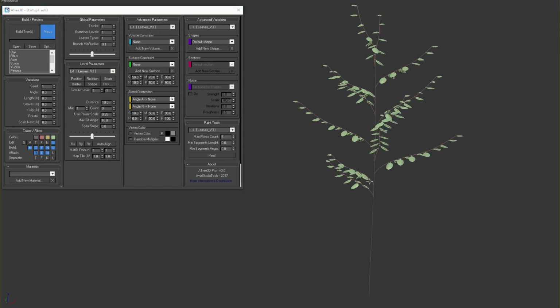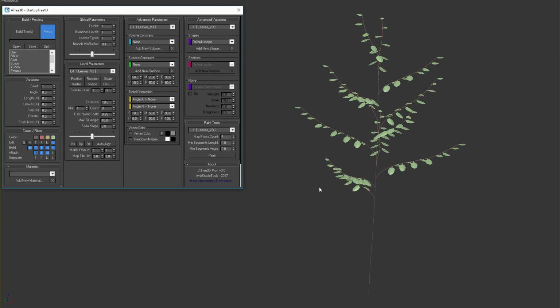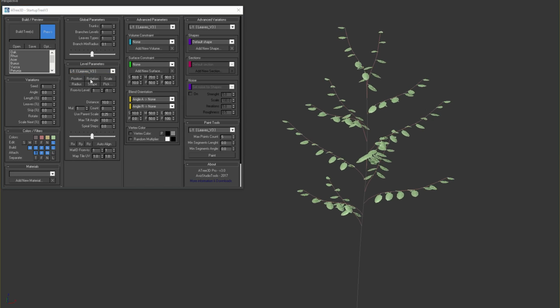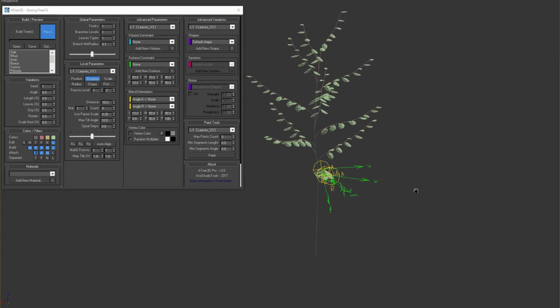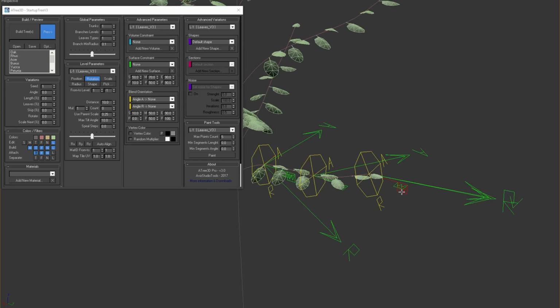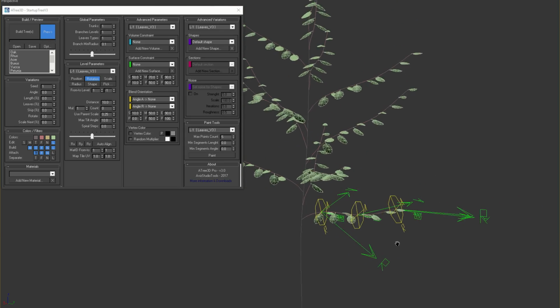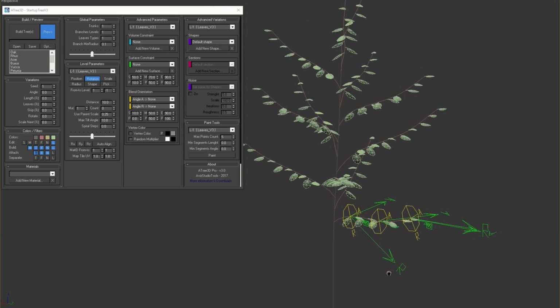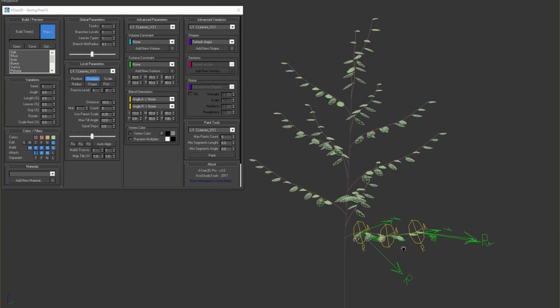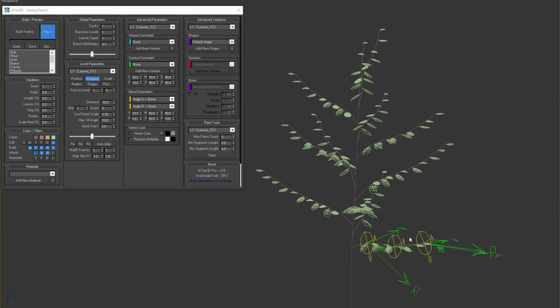Let's continue with the next parameter, Blend Orientation. In this tree model, the leaves are aligned to the world. By pressing the W on the helper, you can change that orientation. Often using only one of the 3 alignments is not enough to achieve the desired result. In such cases we can blend different alignments with the Blend Orientation parameters.